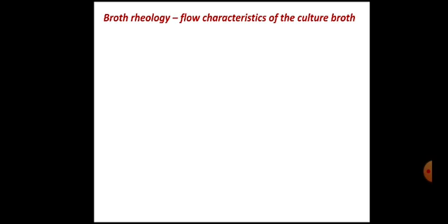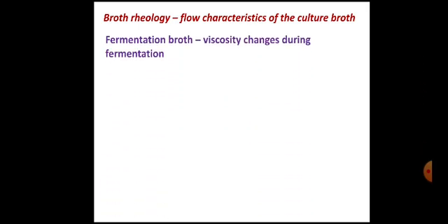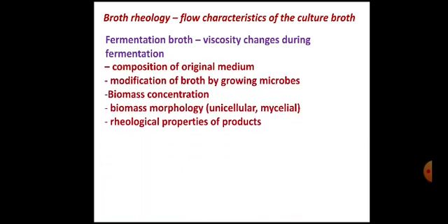Therefore, KLA has to be calculated considering the broth rheology. Rheology means the flow characteristics of the culture broth. The fermentation broth is a mixture of several things, and it may become viscous, or the flow characteristics of this fermentation broth keep changing during the fermentation. Why does it change? The viscosity and the flow characteristics change due to the composition of the original medium.